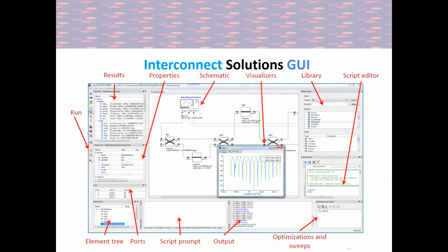And of course, you need to add the S parameters. You need to simulate the losses in the system. The losses can happen during the manufacturing process or whatever. So all of this needs to be simulated accurately. So you combine all of the simulated photonic components from different packages into interconnected packages to create this circuit.